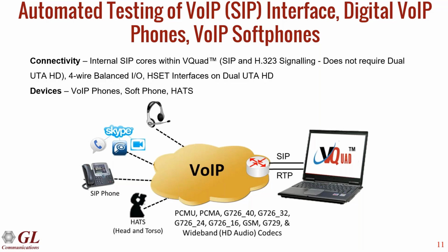Other ways to test a VoIP SIP network would be connecting to an ATA. If there's an ATA to the home, analog telephone adapter, we can connect to the 2-wire interface and then go out SIP. Another way is through the RJ22 handset.